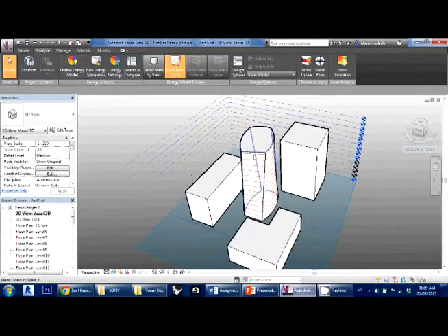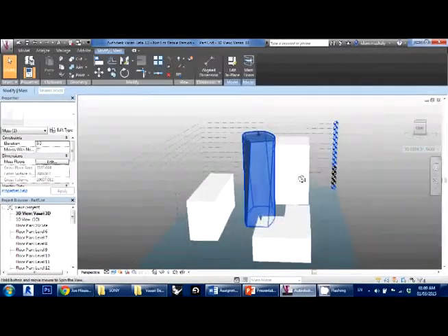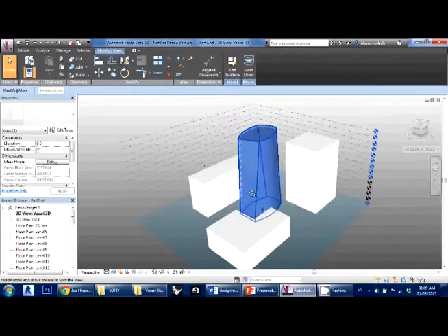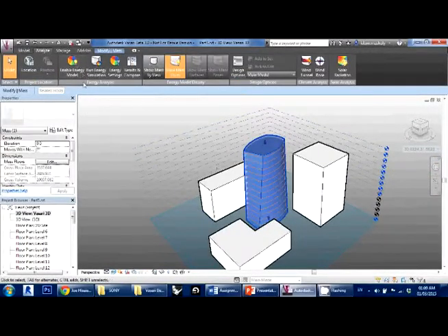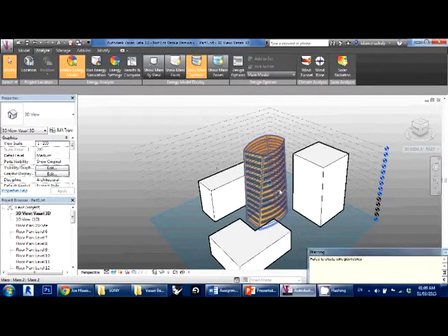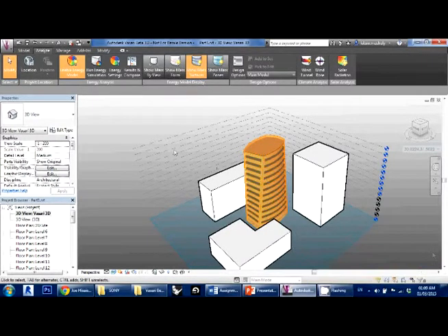So right now I have my floors, but I don't have any windows or any zones yet. To make this happen, I'll start enabling my energy model here. I press on Enable Energy Model, and by the way, this is the energy analysis tab, the part where I do my energy analysis. So first of all I enable my energy model, and I wait until it's enabled. It might take a while because it's a big building here. Okay, I'll skip this warning now.